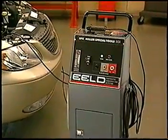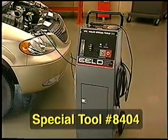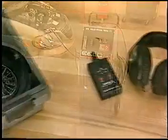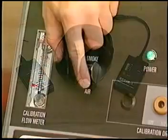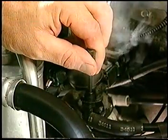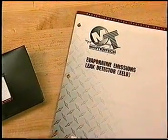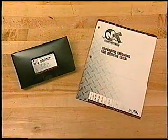The Evaporative Emissions Leak Detector, or EELD, Miller Special Tool number 8404, is used to check either system for leaks during diagnosis. This new tool for leak detection replaces the ultrasonic leak detector used previously. It allows the user to pressurize the evaporative system with shop air and uses a smoke generator to test for small leaks. The smoke generator uses UV dye that will leave signs of a leak under black light. For more information about how to use the EELD, refer to the January 2001 MasterTech program.